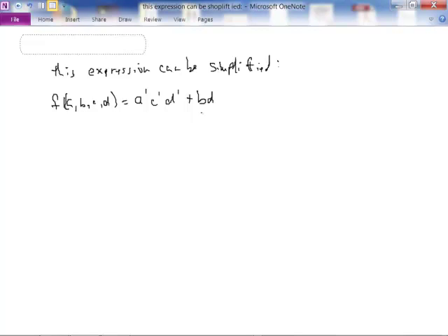So the idea here is that we can hide 1 bit of information in each of the don't care conditions. To hide a 1, we force the function to output 1 on that particular don't care condition, and to hide a 0, we remove the don't care condition from the specification and consider the output to be 0 for that given don't care condition.